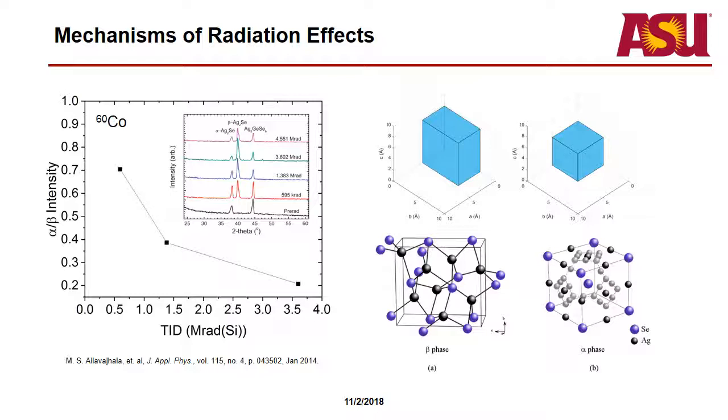But if this material is starting to shift from having this mix of alpha phases sprinkled throughout the electrolyte layer more to the beta phase, then essentially we go from having a super ion conductor that can very rapidly supply ions to the filament to something more like how the copper SiO2 devices are, where now it's a slower process. It's more difficult to get those ions to the developing filament. It takes more energy to do so. And so that's something that we're most likely observing when we do the faster pulses for neuromorphic.